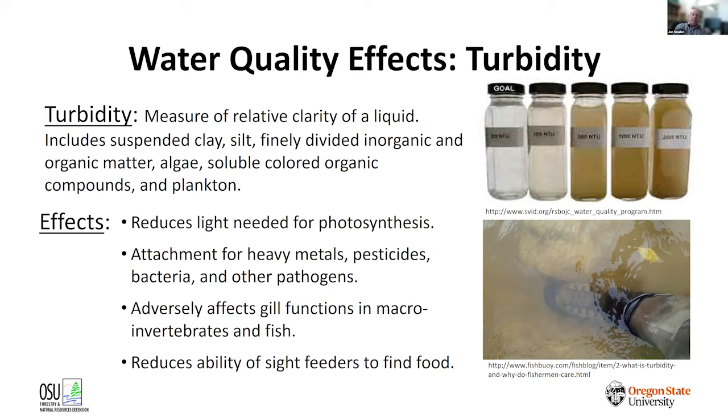And why we're concerned about turbidity is that the major factor in terms of aquatic systems is that it restricts photosynthesis. So we have processes in streams where there are algae photosynthesizing, similarly to the photosynthesis that we get from plants aboveground. So that happens in streams. If there's not good light penetration in there, then that level of photosynthesis is reduced quite a bit.